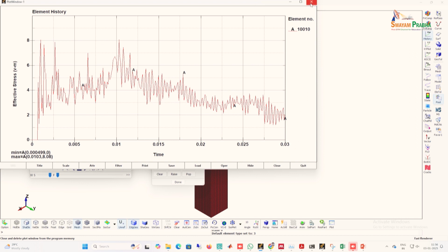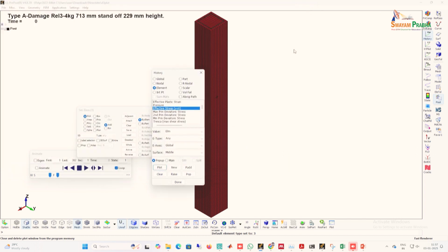And you can cross check. One good way to start a model, if you're working, let's say, as he presented with UHPC, you might have stress-strain curves. So you can model the cylinder, maybe the cylinder that he did, and then match the curves. Then you can adjust the parameters to match the curves, and you can use that. That's one way I've used for high strength concrete.